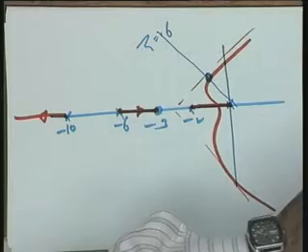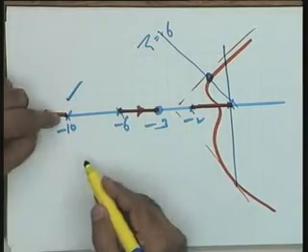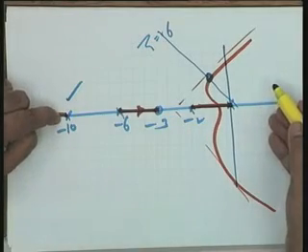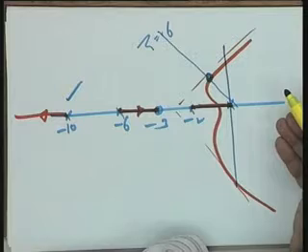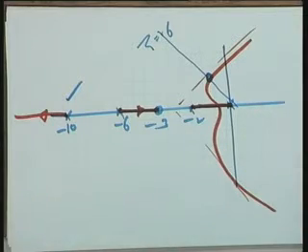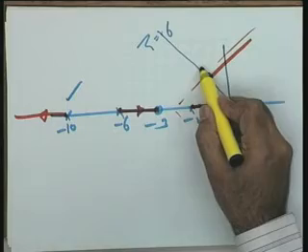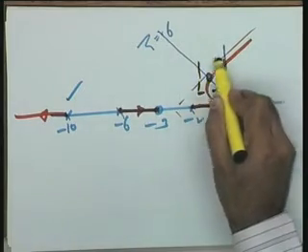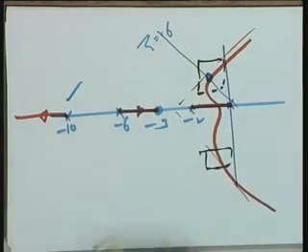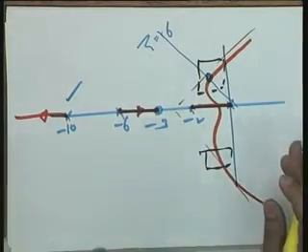It is taken this way. So naturally it means the next pole has a destabilizing effect. It has tilted the root locus this way. But the only claim is this, that you should select a pole here. You should select a filter so that in the region of your interest, the root locus is not disturbed. Let it be pulled this way, doesn't matter.